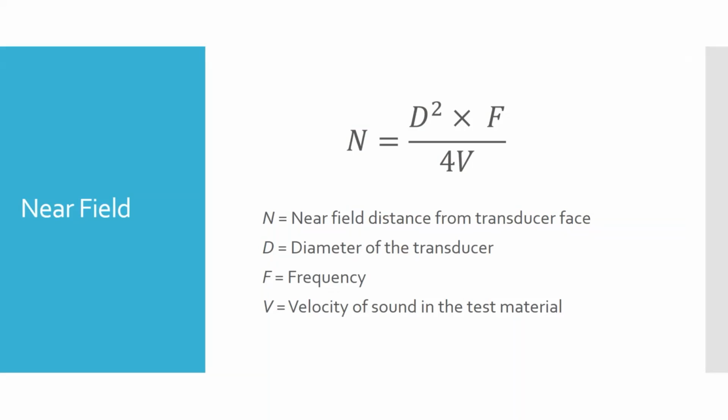Okay, so the near field in this case comes out to 0.0012 meters. Oh, I said centimeters, okay? So it comes out to just 0.0012 meters, which is, move that over, it's 0.12 centimeters, which is just over 1 millimeter into our part.